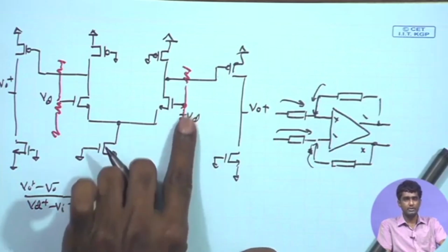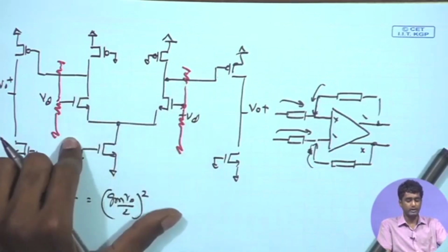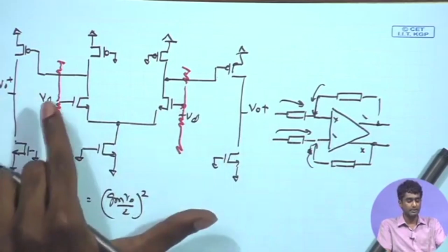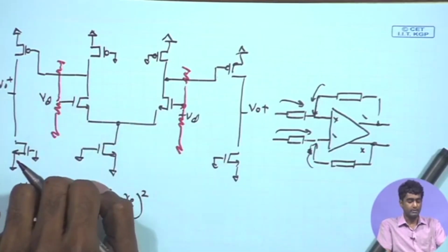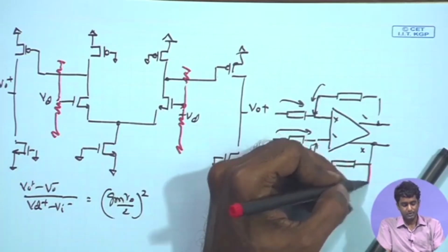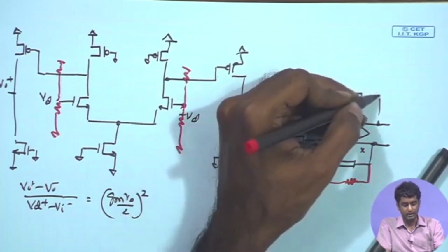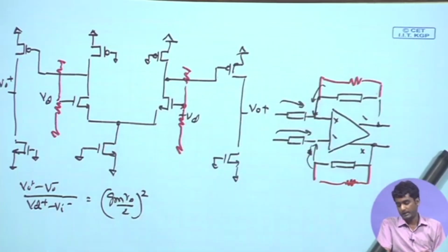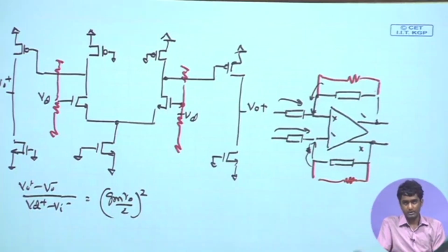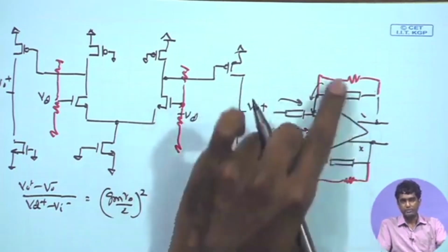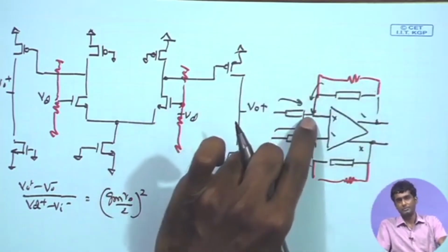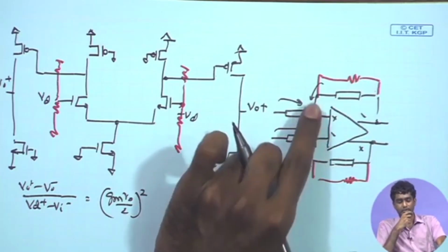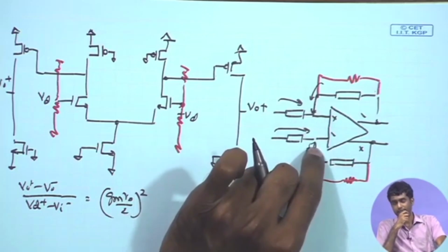So rather than using voltage dividers at the input port, we are going to take help of the already established DC bias point at the output to bias my input nodes, and for that we are going to use resistors in parallel with our feedback element. Let us see how this helps, and how this does not violate our other constraints. So we have to choose appropriate values of this R and make sure that it is helping us in establishing the appropriate DC bias point at the input terminal of our differential amplifier without violating the frequency response or the noise constraint of our overall amplifier.